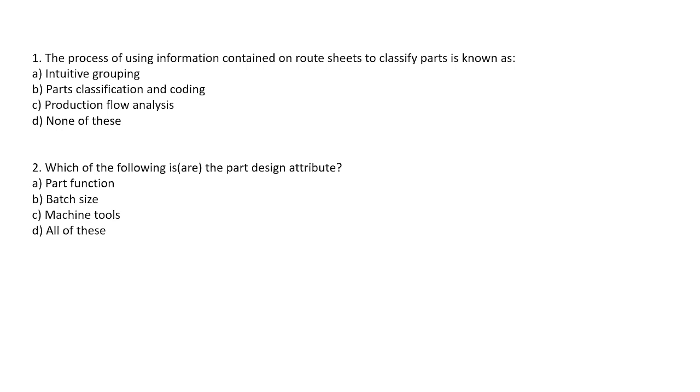Standard process plans can be developed for the groups, and standard tooling and setups can be developed for a part family, which allows faster production, less inventory and work in process. Throughput time also gets reduced, and material handling and movement are reduced. Those are a few of the benefits of group technology in a manufacturing system.